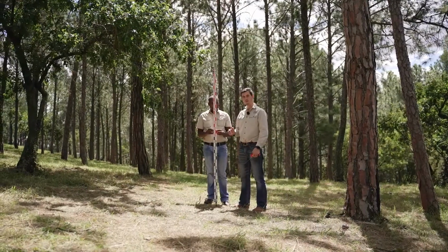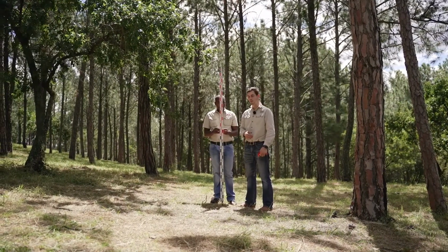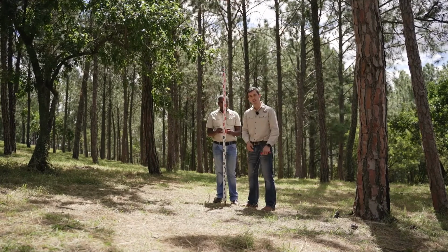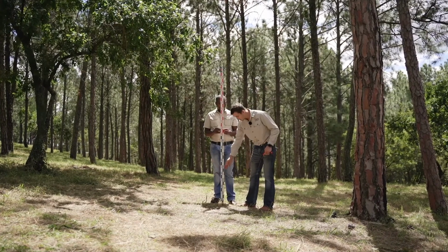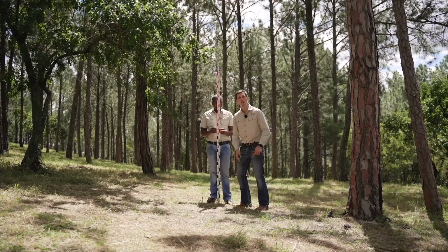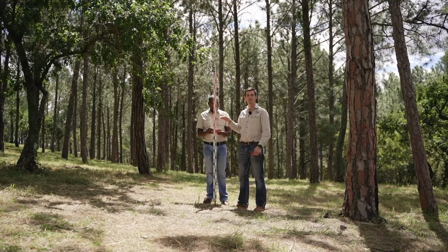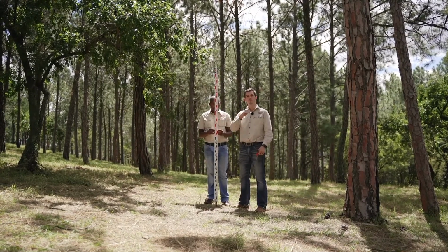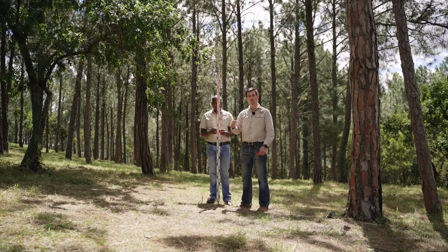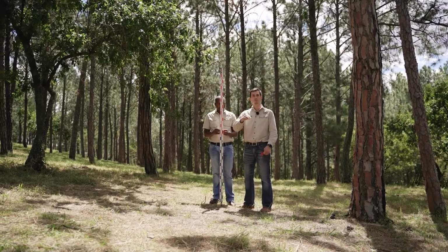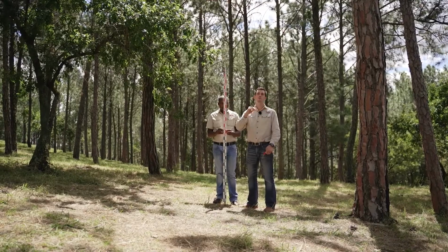When you use a staff, there's a few methods that you can use. The first one, if you've got an existing benchmark on site, you can place your staff on top of that benchmark, read it with your dumpy level, and use that as a new and existing height, which you can transfer to the rest of your site. If you've got a platform, you can use it to establish the correct height on all your platform corners.